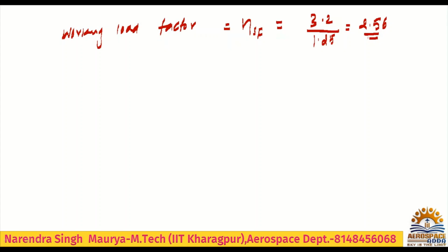Now we have to calculate the speed during the sudden pull up. If you say pull up and sudden pull up, that is a different word. Pull up or pull down is a different case. At that time you need to write that the resultant upward force is equal to centrifugal force. That is true, but here it says sudden pull up, so it is a very short period of time, a time instant. Otherwise, if it is pull up or pull down in vertical turning, the resultant force will be L minus W is equal to centrifugal force.